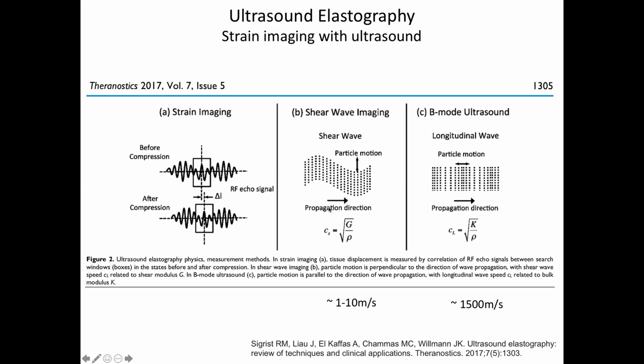So first, let's take a look at these two things. What is a shear wave? A shear wave is if I have a connected set of particles, right? And say I have a 3D array of connected particles, and I got little springs between each ball. And I take one face of that large array and I move it up and down. A wave will move in, say, the X direction, with particles going up and down, right? That's a shear wave. Like when you're surfing, because the wave is moving from the ocean towards the beach, but the water molecules are moving up and down.